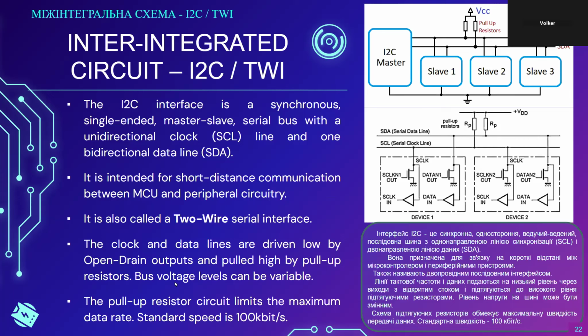You could do that, for example, with an I2C EEPROM. You just need essentially 2 wires, plus power and ground, so 4 wires. And as long as the impedance and the length of that line is defined by the developer, using I2C for short off-board connections is a relatively common occurrence.